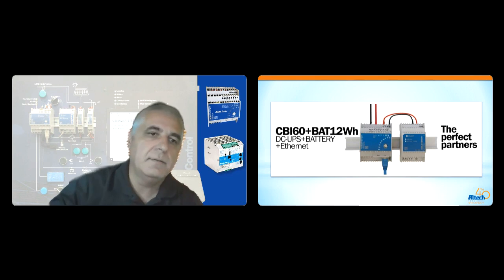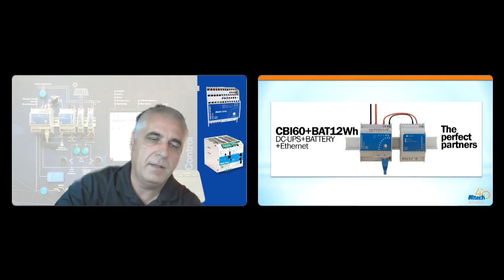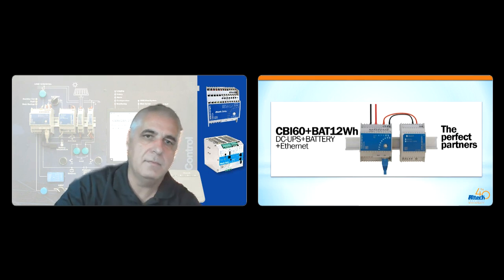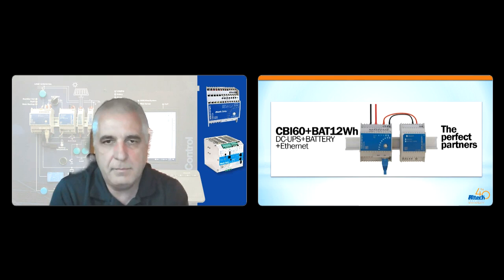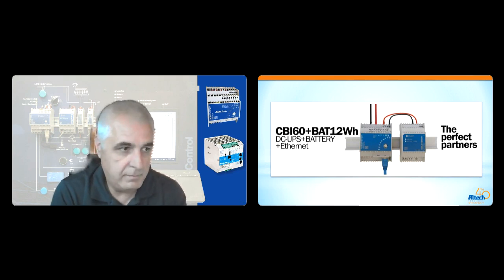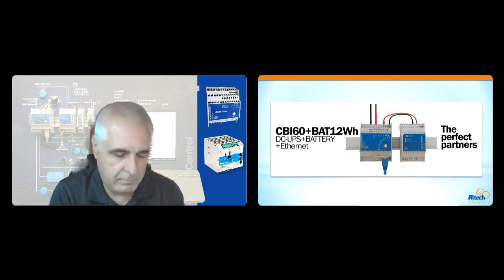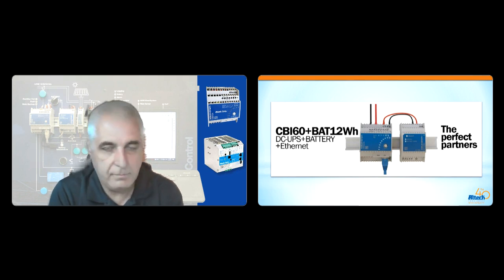Yeah, I have a lot myself, but in manufacturing, if your machinery is going and you lose power for half a second, all your PLCs shut down and then manufacturing stops. But if it's only for a brief second, the UPS will handle that, and your PLCs don't go down. And so manufacturing continues, instead of everything stopping, PLCs going down, then having to reconfigure the whole piece of machinery.